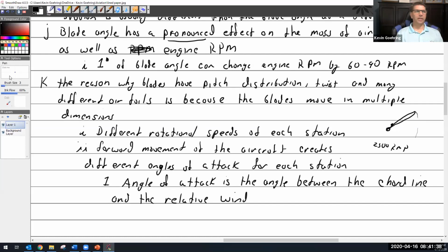So if I have an airplane, and unfortunately during this part of the class, I do a lot of hand gestures and motions, so you kind of have to look. If I have an airplane and the airfoil is flying this way, my angle of attack is coming right at it. But you see high performance F-16 jets, maybe going to high angle of attack, and they're still flying this way. My angle of attack changed dramatically because it's still flying this way. But if you get an F-16 that's going straight up this way, then the angle of attack is this way. So it's relative. It's not necessarily the wind, but where it seems like the wind is coming from to the wing, or in this case, the propeller.